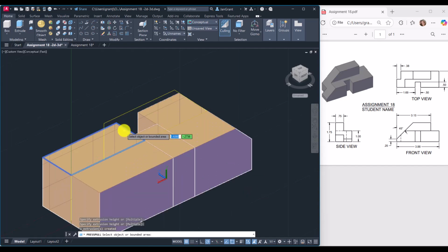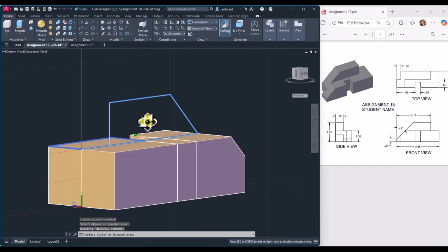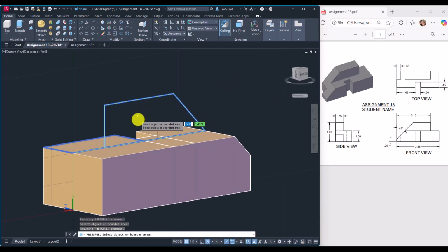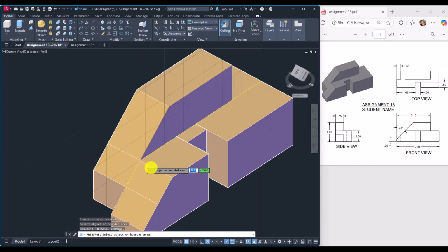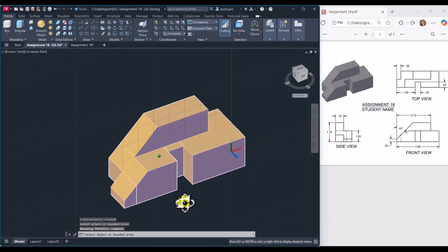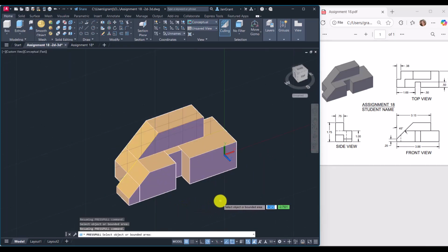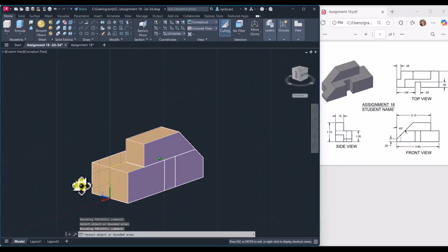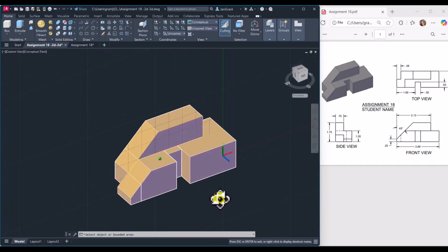And then this is the tricky one. You may have to move your mouse around like this and move your mouse around. You see what I mean? I had to orbit around until I could kind of see the line work. And I can click in here and pull that over and click. And that is the model. So we went 0.75 out from that middle piece, because we have a flat piece on the back, all the way around. It should look sort of like that.